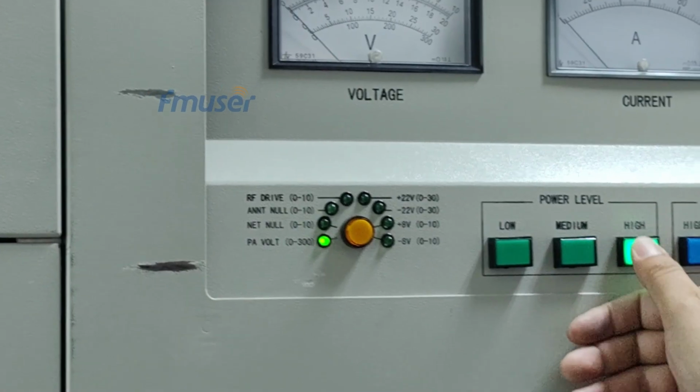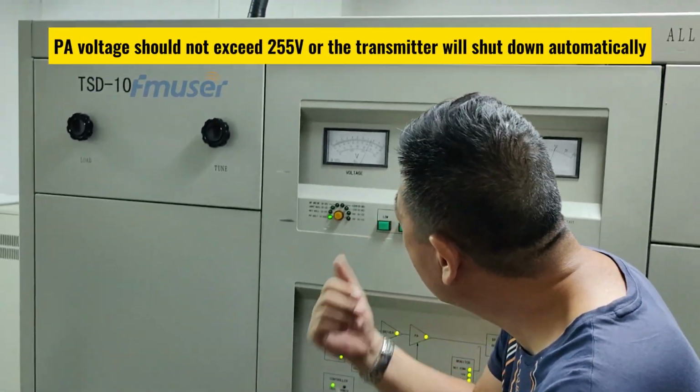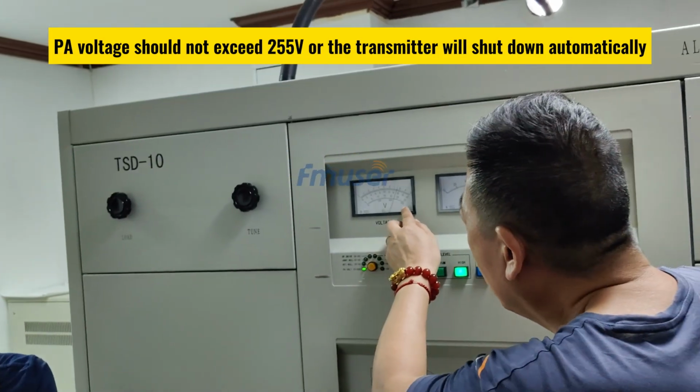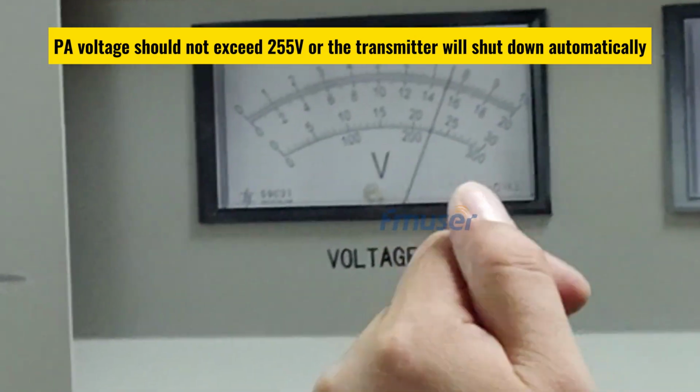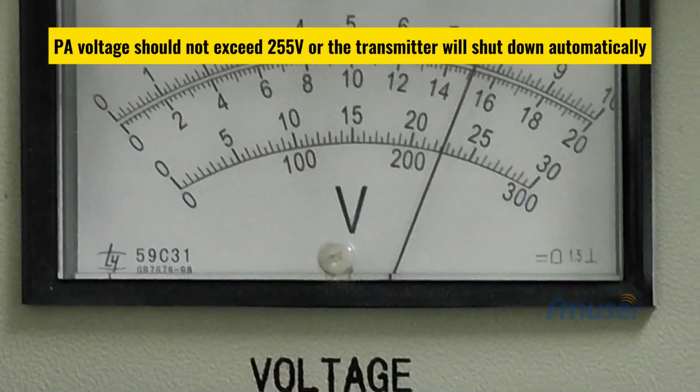Click high in the power level area to set the output power to 10 kW. Be aware that external factors may cause fluctuations in the voltage of the PA module within a 10 volts range, but it generally stays below 255 volts. If the voltage exceeds this limit, the transmitter will automatically shut down.